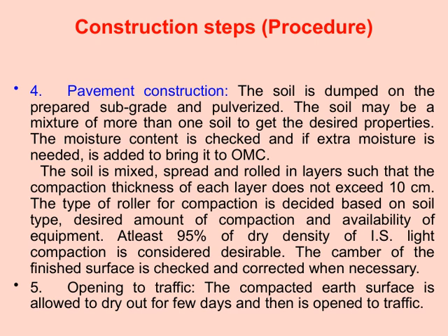After compaction, we check the camber, or the slight slope of the surface, to make sure it's correct, and if needed, we make adjustments. Moving on, once the surface is properly compacted, it's allowed to dry out for a few days. This drying period ensures stability before opening the surface to traffic. Only after this drying phase is complete do we open the pavement to traffic, ensuring durability and safety for users.